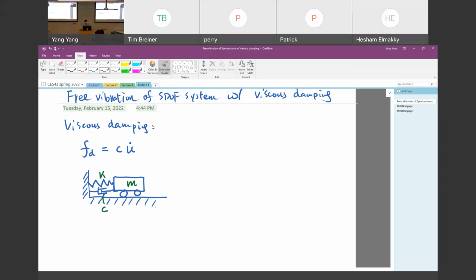So where does the damping come from? Actually, even nowadays, the cause of damping is typically due to, for example, for structures, the friction between different components, such as in wood frames, between wood beams and the columns, contributing to the primary damping over there.